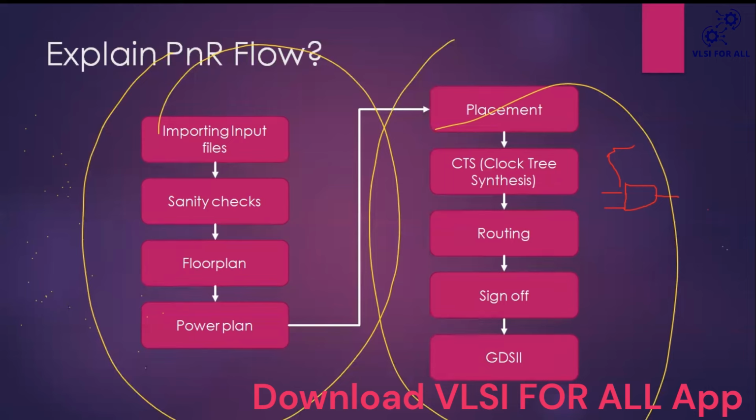After that comes placement. During placement, the tool mainly follows power driven, congestion driven, or timing driven; there are three types. In area-driven placement, it will try to use all the available area properly.